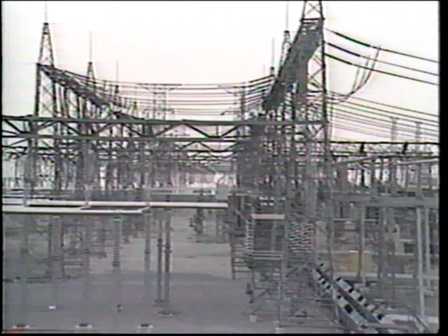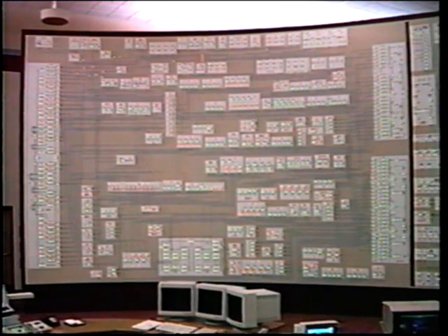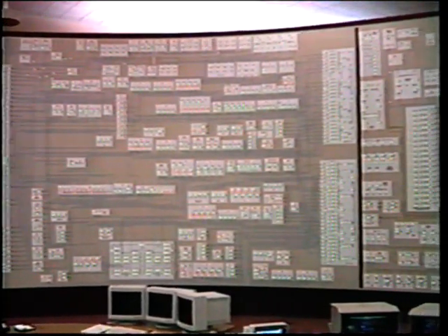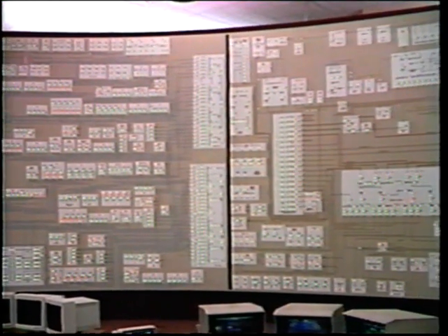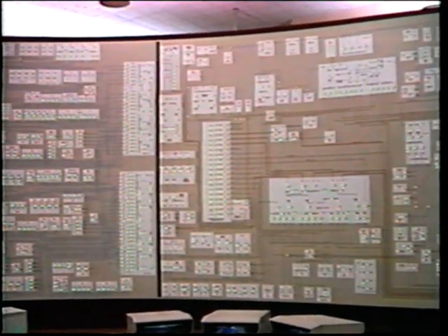First, you should recognize that we cannot monitor every voltage and current in a particular installation. Many older recorders are limited to 32 channels of information. New digital machines allow 64 channels or even more. Either way, the precise data to be monitored must be carefully selected to get the maximum amount of information after a fault has occurred.